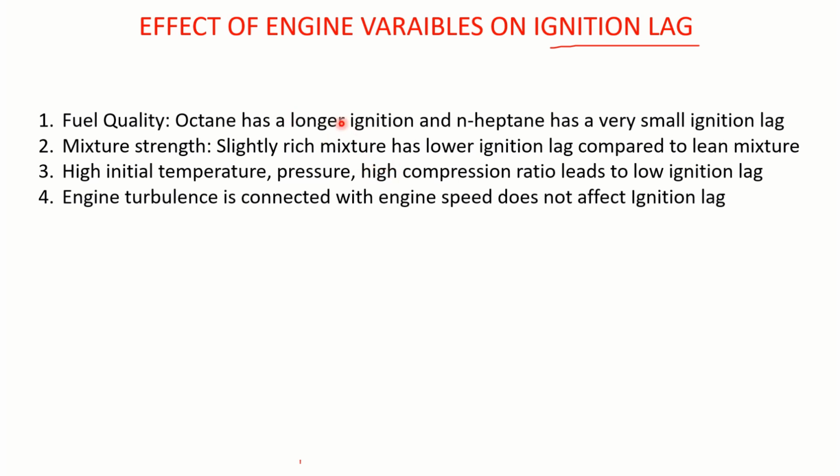If you want to increase ignition lag to avoid abnormal combustion, then it is necessary for us to reduce the compression ratio of the engine. If you reduce the compression ratio, then the thermal efficiency of the engine will come down. So there are many repercussions of this.